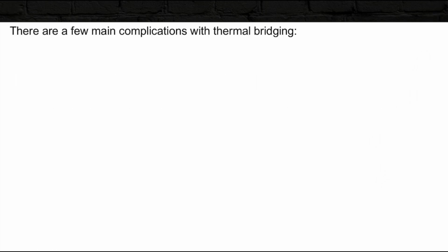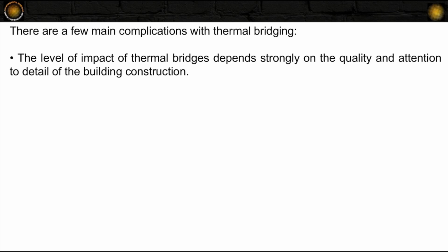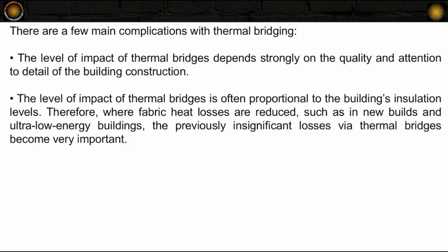Now, the main complications with thermal bridging: the level of impact of thermal bridges depends strongly on the quality and the attention to detail of the actual construction, i.e. has it followed the plan to the letter. It's often proportional to the building's insulation levels, therefore where fabric heat losses are reduced, such as in new builds and ultra low energy buildings, the previously insignificant losses via thermal bridges do become very important.